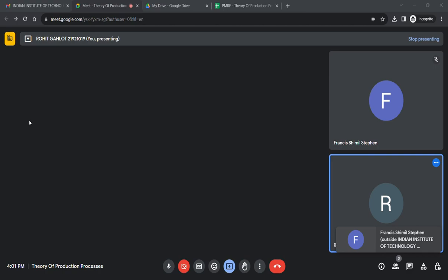So we can use this for cube and cylinder. You can use the V by A formula for D by 6, for cube and cylinder, right? But the main thing which you need to remember, taking into your heart, is V by A. And this V by A of a riser should be greater than V by A of the casting. If you forget this, then we won't be able to solve the problem.